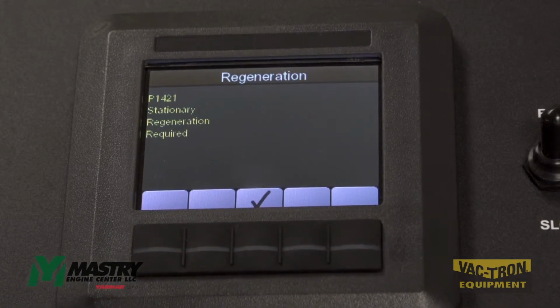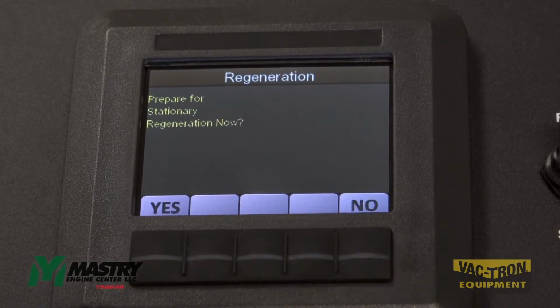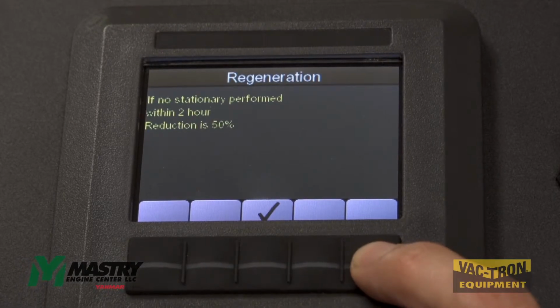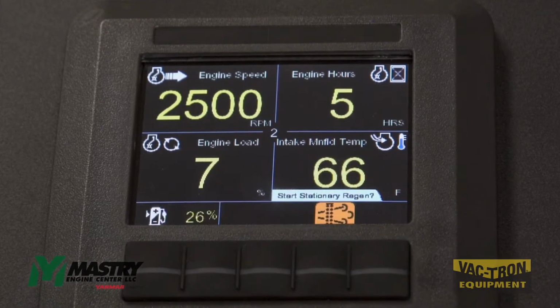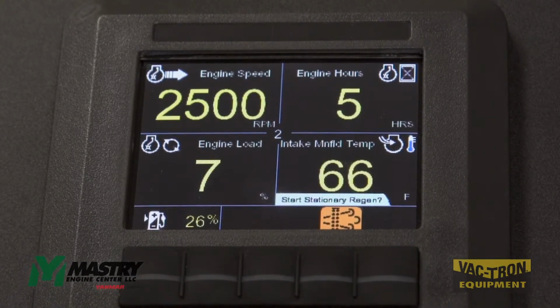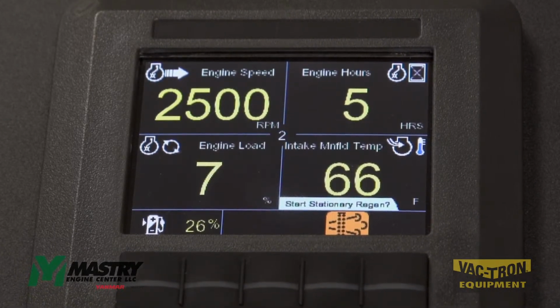If the engine requests a stationary regen and for some reason you're in the middle of a job and you're not able to do the regen, you can acknowledge and instead of preparing for the regen, say no to finish what you're doing. At some point you will need to perform the stationary regen, otherwise the aftertreatment on the engine will become clogged and the engine will derate and render itself useless.